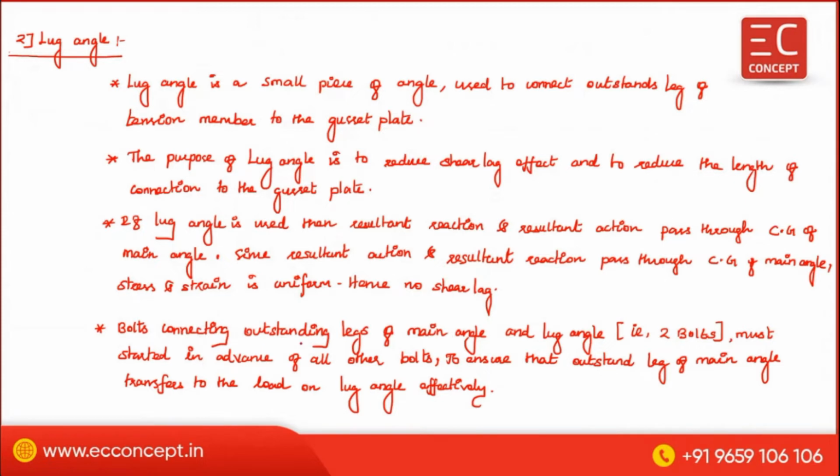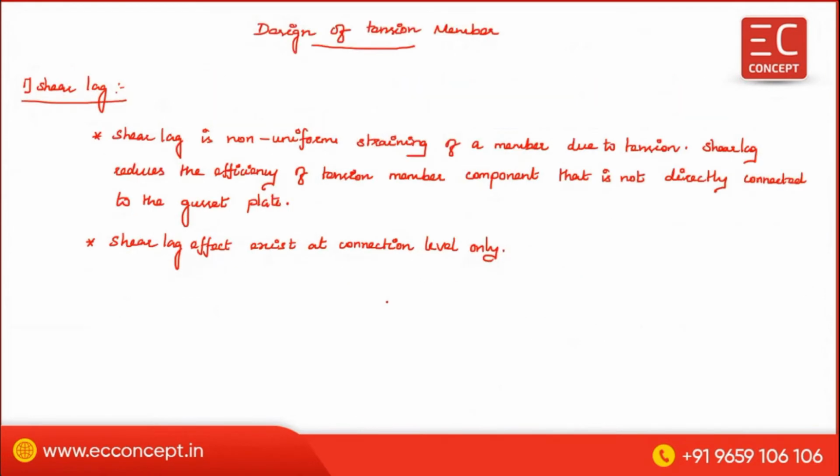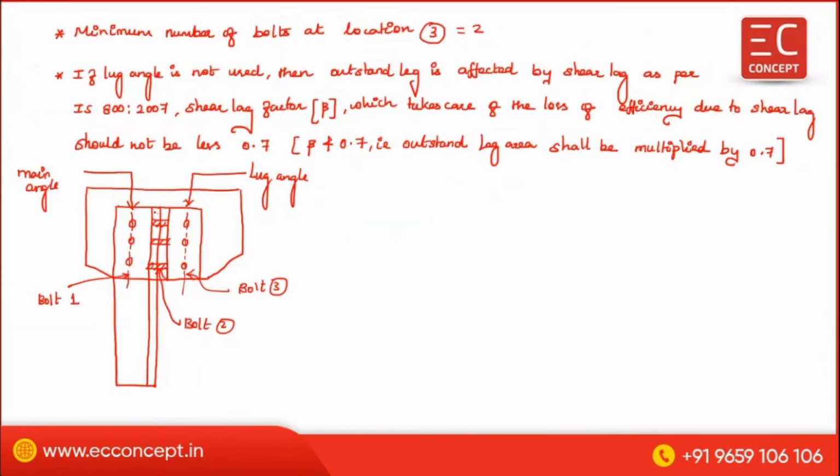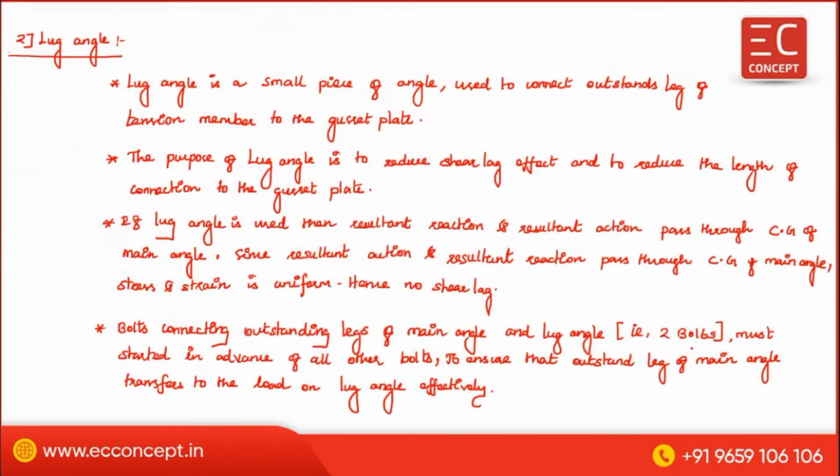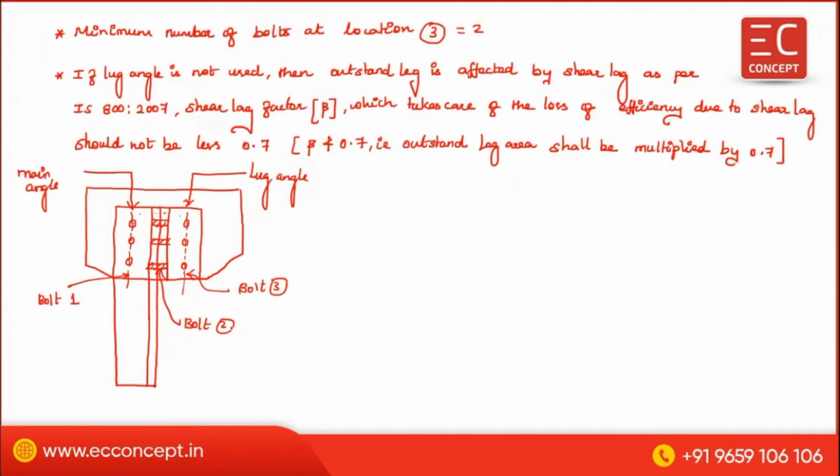Both connecting the outstanding leg of the main angle and the lug angle, that means this one. The outstanding leg of the main angle and the outstanding leg of the lug angle, these two must be started first. The first thing is you have to connect these two outstanding legs.